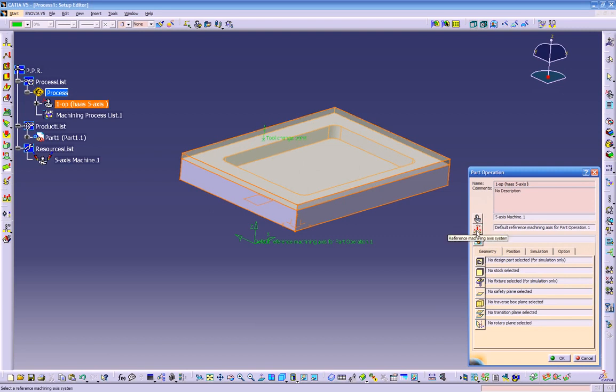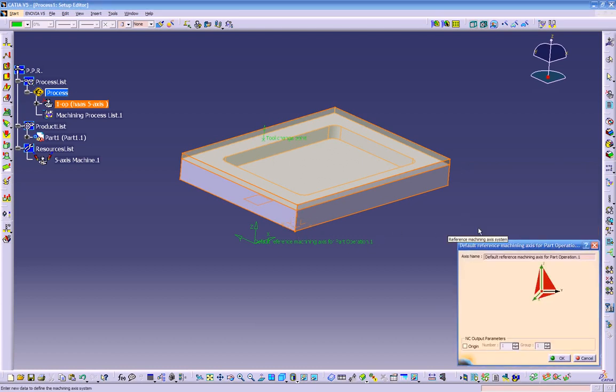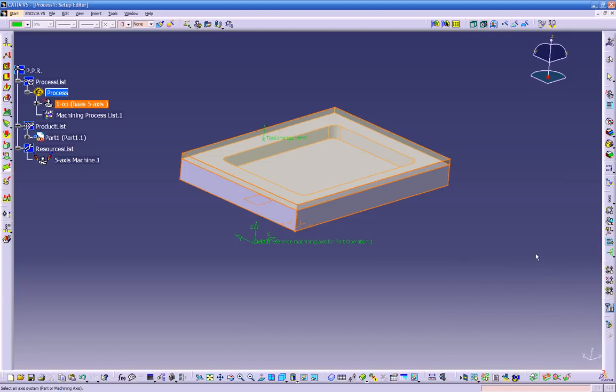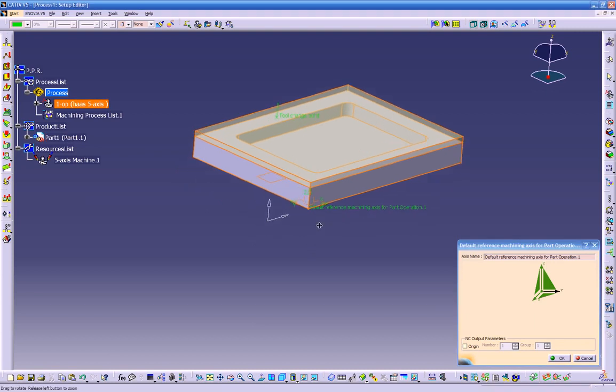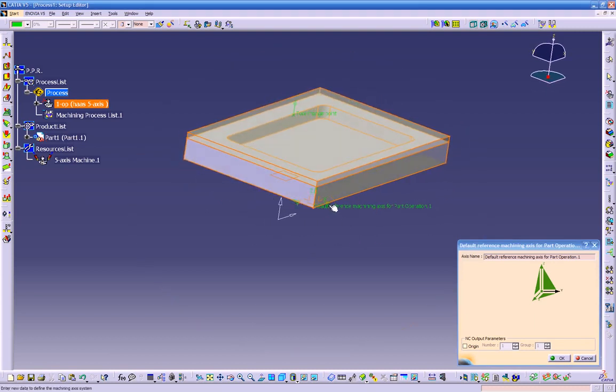Now we have to go next to create our axis. See, our axis right now it's over here, but we have to make sure we specify our new axis. So let's click on axis and click anywhere on the red area. Okay, and it's gonna ask you to select, on the bottom left hand corner, it says select an axis, and we just click on the new axis that we just created earlier, and automatically it's gonna snap in place.